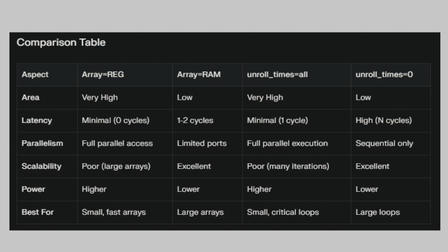So these are the two different optimizations that we can perform on an array. Coming to the loops, we have a concept called unrolling, where the for loop is unrolled or opened up, and each iteration in the C code is written one after the other instead of all being combined inside a looping function.